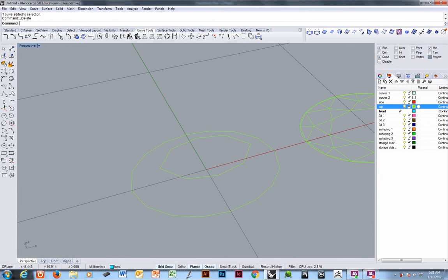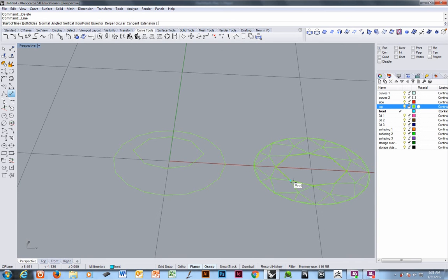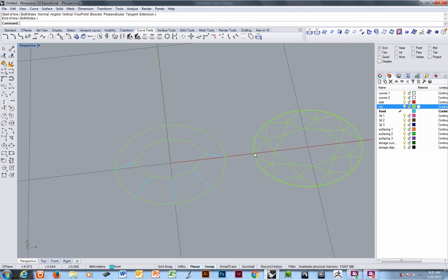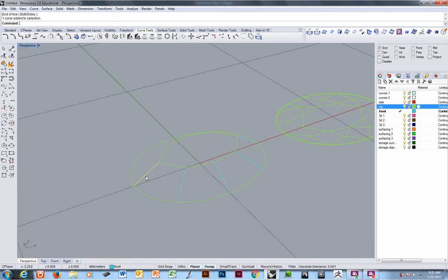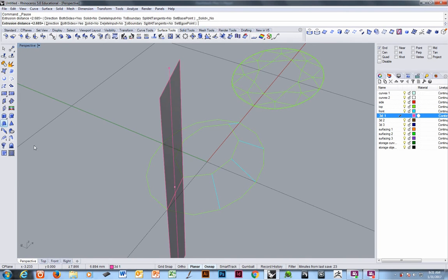I'm going to draw some connecting lines. The important lines for faceting a stone are the lines down the center of the bezel facets. These are your large planes that they first cut when they're faceting a stone. We're going to replicate that information by drawing lines connecting the girdle and the table that would bisect or cut in half each one of these bezel facets. Going to now extrude surfaces, straight surfaces, planar surfaces, from these curves.